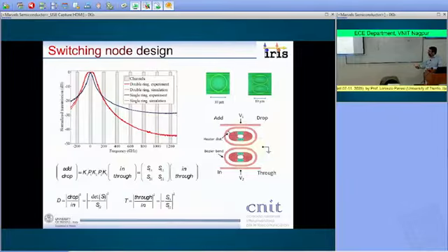The first one is that we reduce significantly the crosstalk, so we increase the isolation, as well as we have a transmission of the two ring resonators which has a flat-top shape, meaning that we are not deforming the light signal that is propagating in the desired channel.